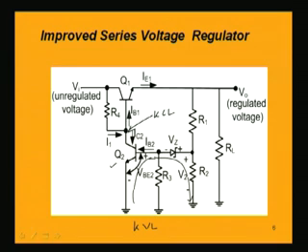The direction of the base current in the first transistor will be towards the transistor, because it is an NPN transistor. The P must be positively connected, so the current direction will be like this. That means at this point I1, the incoming current, equals the sum of the outgoing currents IC2 plus IB1.